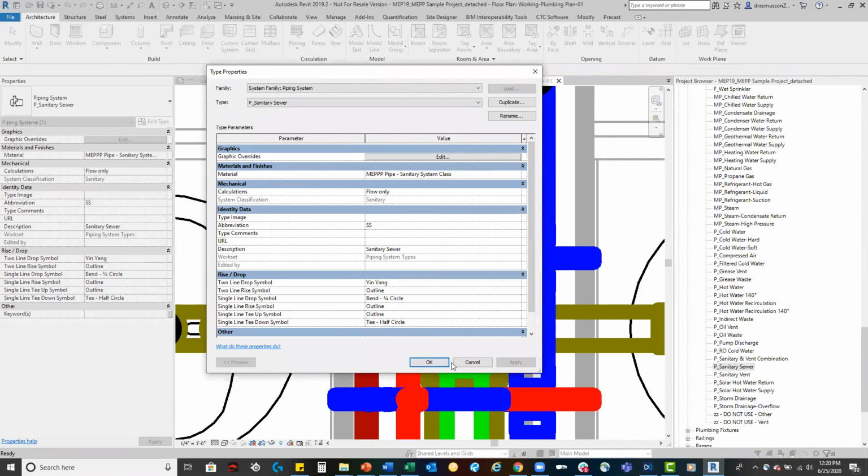And system split connections and fittings, guys, have a huge role to play, not just in plumbing. They can exist for hydronic, they can exist for ductwork. System split fittings is a big way to get around the cross system issues, you know, if you're thinking outdoor air into return air or supply air, right? However we have to do that, you can just simply take some of these fittings, redesignate the connectors, and move forward in that vein. And that helps fix a lot of it.